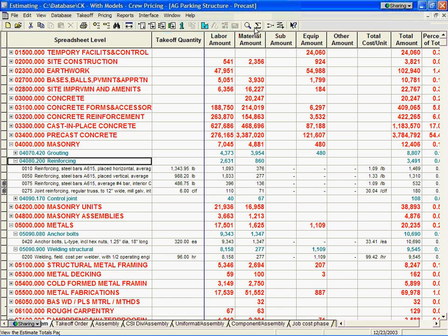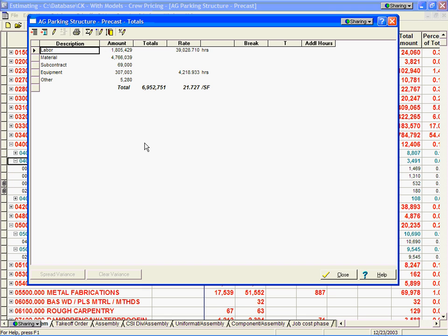Bottom line where we are, if I look at this right now, based upon the numbers we got in our database, we're at $6.9 million. Now, one of the things I said we had with the RSMeans database is 700 plus cost indexes. If I were to open up an RSMeans book and look at the price in the book, the price in that book would be a 30-city average. So it takes the 30 top metropolitan areas in the United States and Canada, and it averages those 30. Those are the prices that you see in a book. You go to the back of the book and you index that price for the location that you're looking at. So this happens to be based upon the 30-city average, $6.9 million,